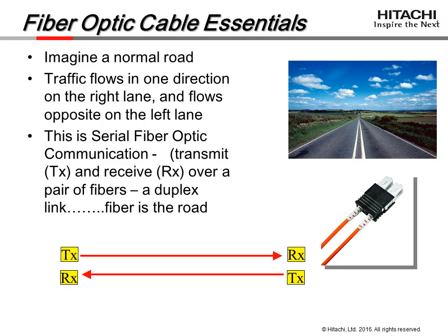Most applications that utilize fiber optic cable require a pair of strands to operate. One strand accommodates the signals being sent, while another strand handles the signals being received. When installing a fiber optic cable, it is best to install a cable that has more strands than you originally need. This offers redundant strands and allows for future growth. Fiber optic strands are also typically installed in even numbers, with 6, 12, and 24 strands being the most popular.